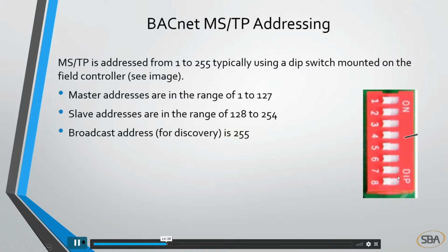Let's talk through addressing a little bit here. In the past, addressing used to be done with dip switches. Nowadays they finally figured out, hey, maybe we should put this in the controller to make life a little easier. There are two schools of thought on that. You can put it in the controller and have it done by software, but then you don't have a visual representation of what the address is. But if you have it done by hardware, people who can't add are going to have a little bit of a challenge.